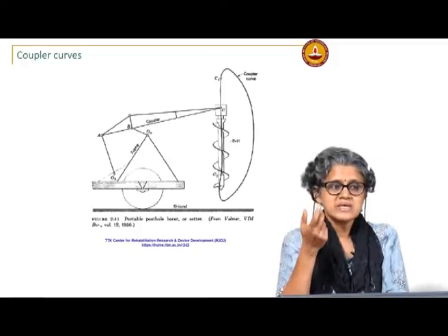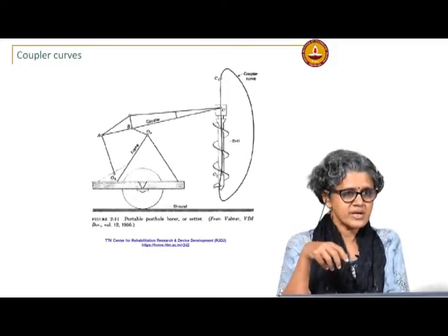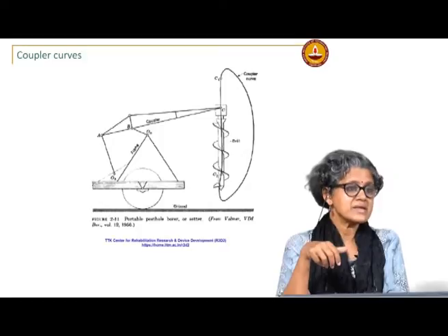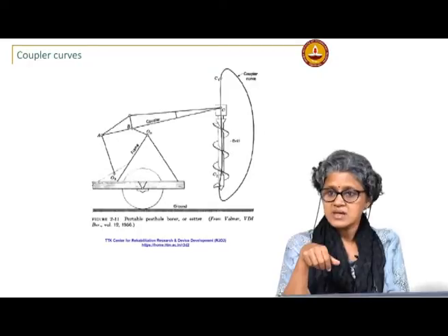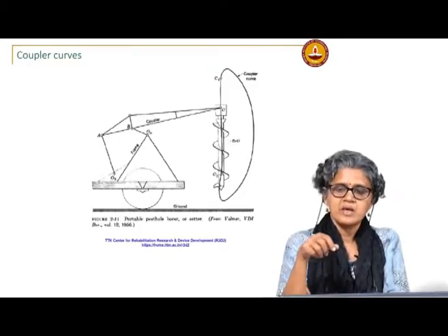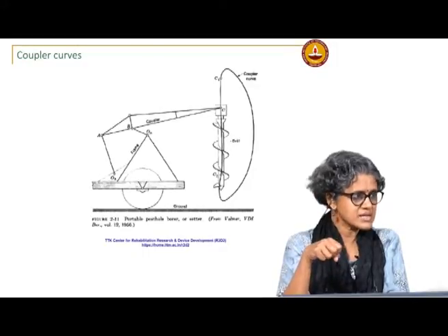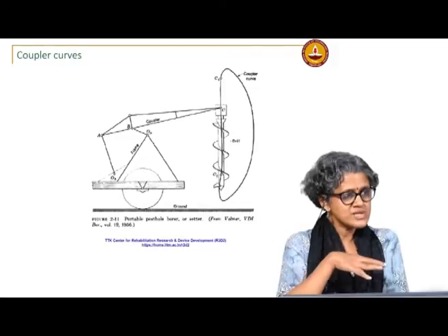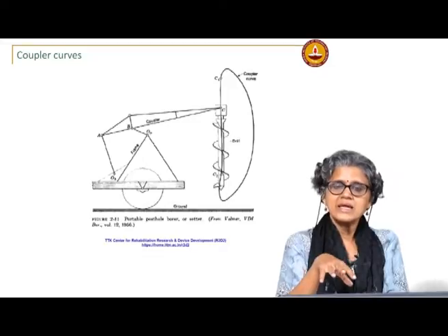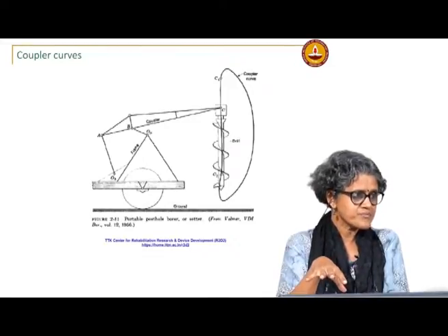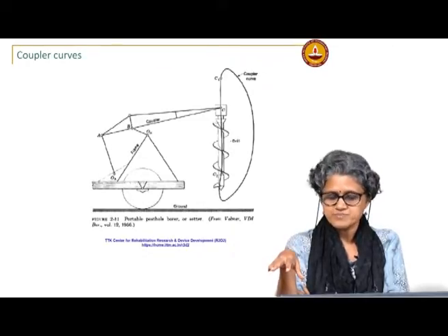Okay. So, in places where you may have had to use, see the problem with a prismatic joint is the maintenance of it. First, manufacturing it to a certain level of precision is difficult, and then maintaining it, because if anything gets into it, the prismatic joint can really stick. Okay. Revolute joints are a lot easier to maintain. So, if you can do something with a linkage with only revolute joints, that is a better option than going to a linkage with prismatic joints.